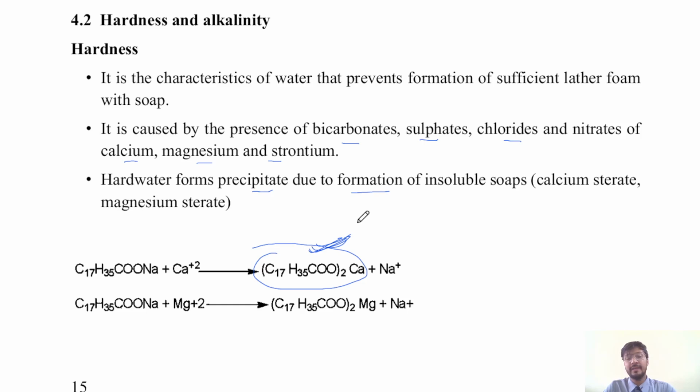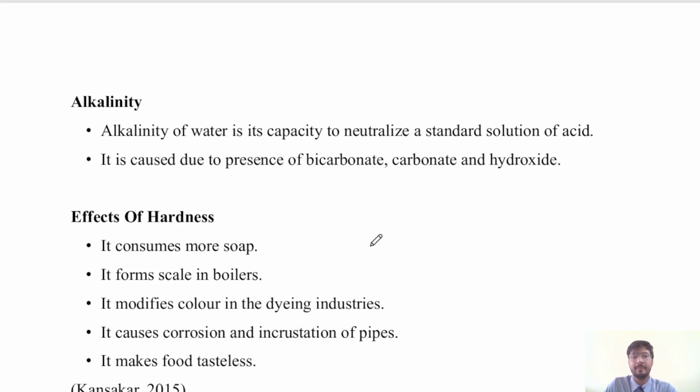Hardness is caused by dissolved salts of bicarbonate, sulfates, chlorides, and nitrates of calcium, magnesium, and strontium. These ions react with soap to form insoluble scum like calcium stearate, which floats or settles instead of forming foam.